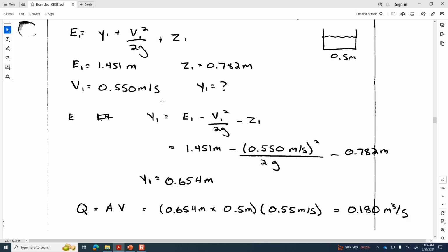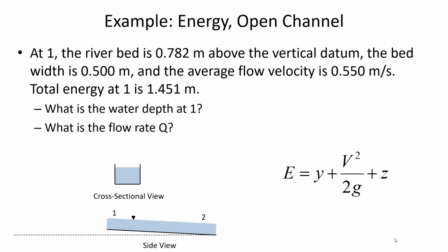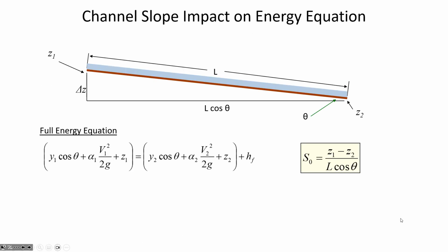And so we will come back to this, but for now, remember, when we're dealing with steady and uniform flow conditions, it's the momentum equation that we use to solve for the flow depth, not the energy equation.